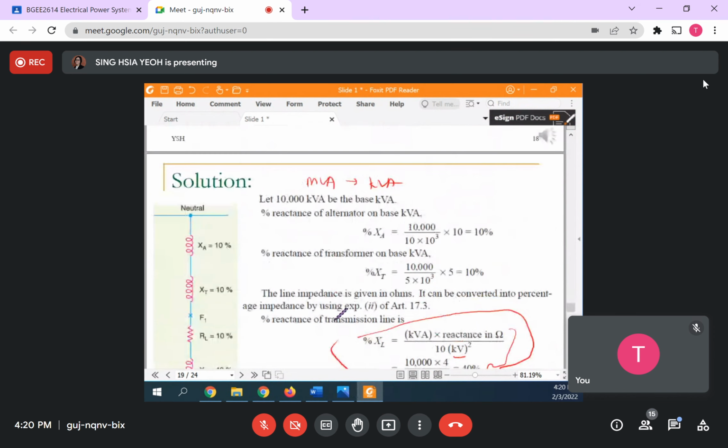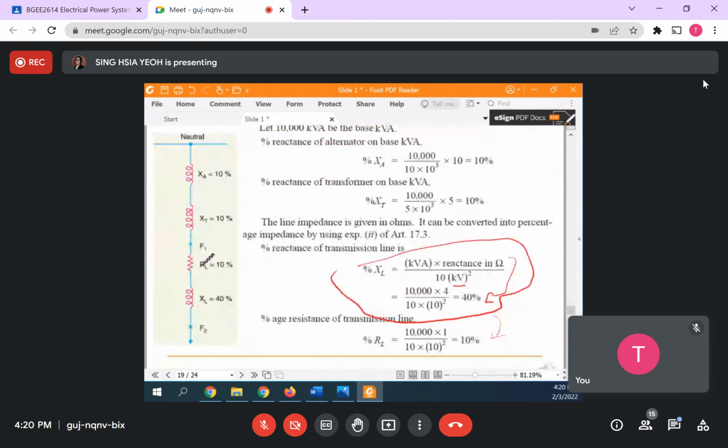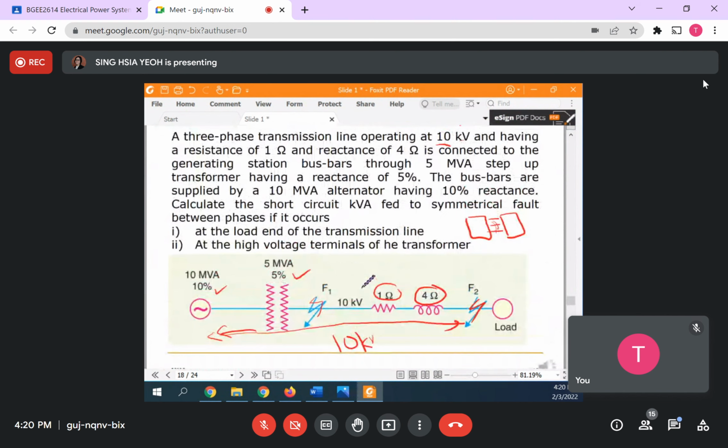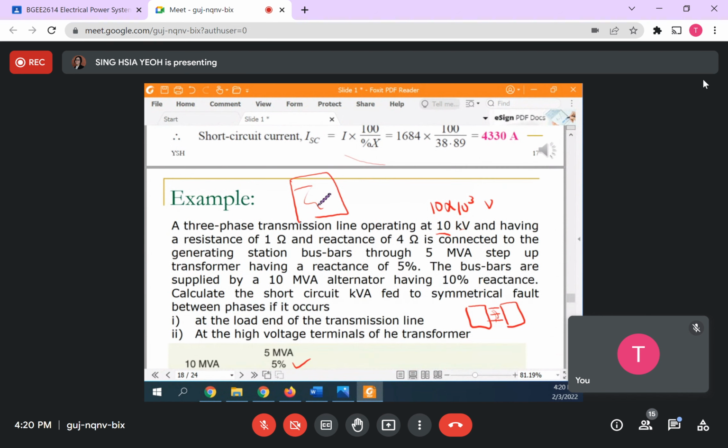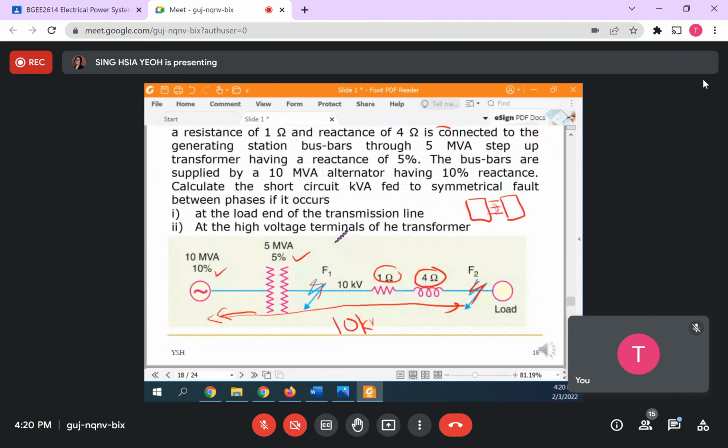But so far, whatever value they give you, you just use. Once you change it to the impedance diagram, like in your PU chapter, whatever line is stepped up and down according to the transformer ratio. They give you a base value, then you step up and down according to the transformer ratio, and we won't care whether the voltage is phase or line voltage. We just use the voltage and continue our calculation.